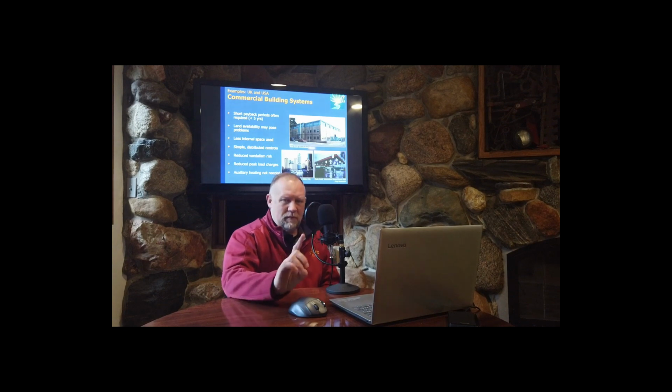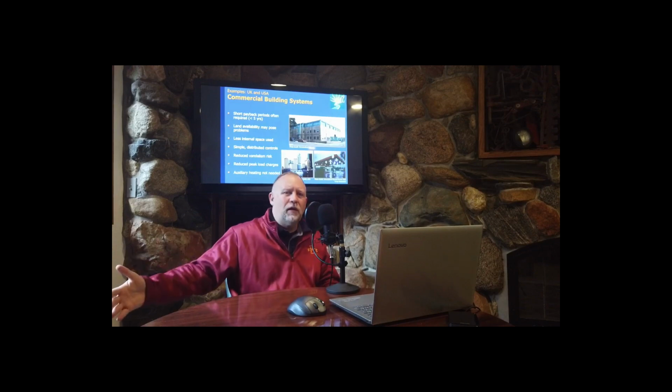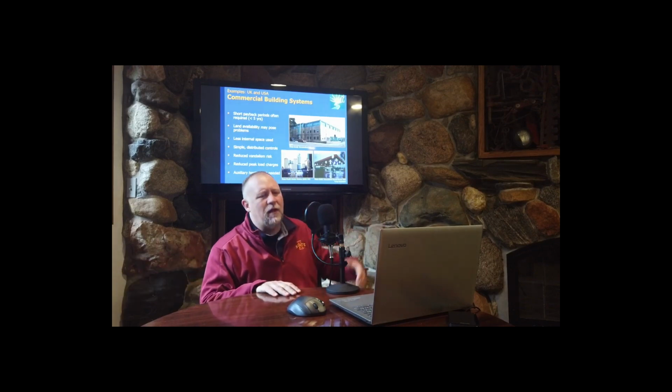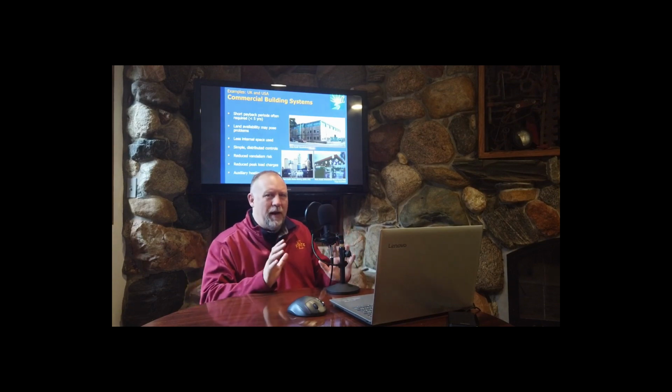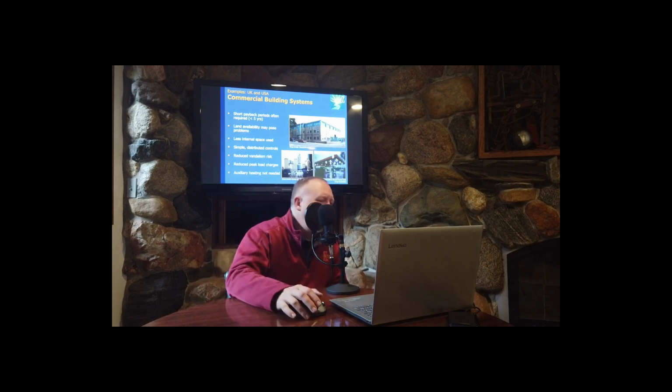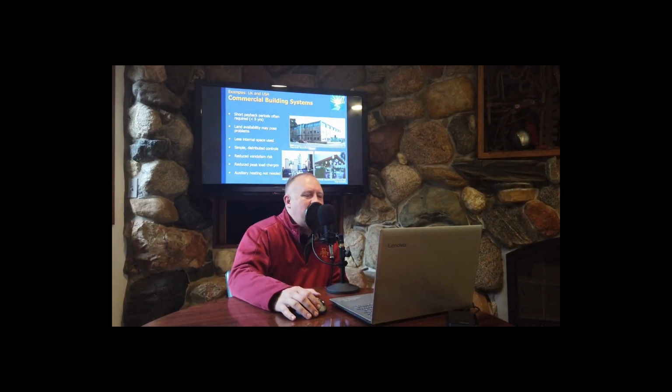Now, something important to keep in mind is that you can't build on top of them. You can't put a parking lot on top of it, and you can't put a building on top of it. So wherever you put those tubes, even though they're buried and out of sight, you can't really put much on top of it. Because those tubes are not visible, we have a reduced vandalism risk, which is true, and that's something that buildings do worry about. All right, let's keep going.